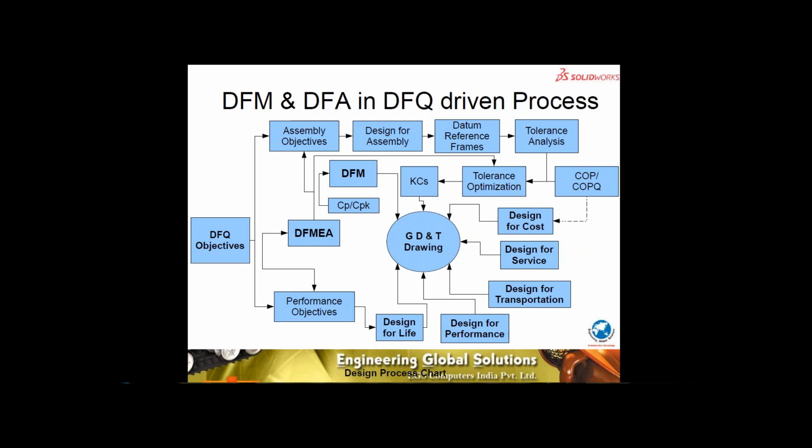The weld in a system leads to what is called heat affected zones, leading to shrinkage and loss of tolerances after the components have been welded together. Can we study it? Yes, you can. With an integrated product design and process selection as a part of the product development process, these are all enabling technologies at the design stage to address the design for manufacturing and assembly requirements.